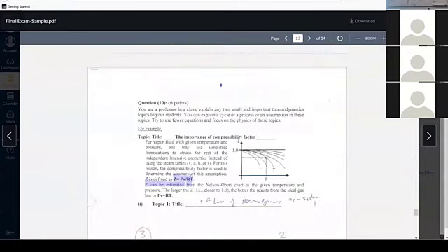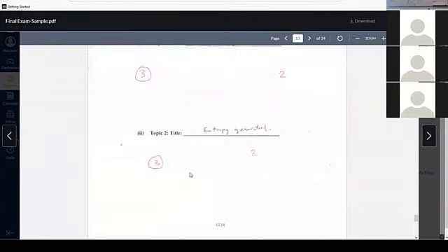So the ideal gas law is a very powerful law. You can simply solve an engine without a table. Just one simple equation and other equations like delta U, delta H, delta S for ideal gas. But first, make sure it's an ideal gas. So you need to avoid the steam table. We can solve Brayton cycle, Otto cycle, anything without having tables.